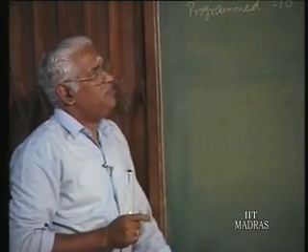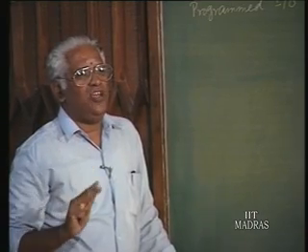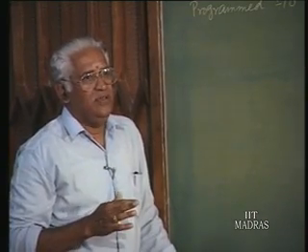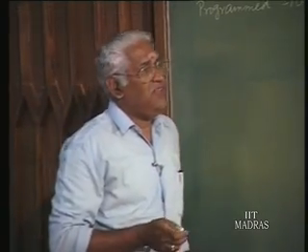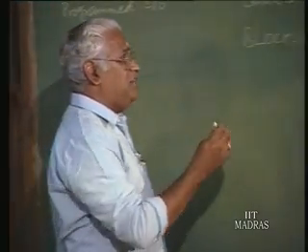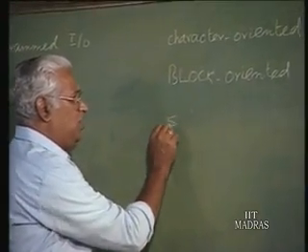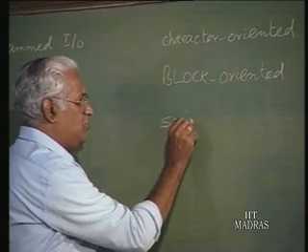first, what is programmed I/O? First you have to check whether the device is ready. We know that the device being ready can be checked by looking into the status register, is it not?